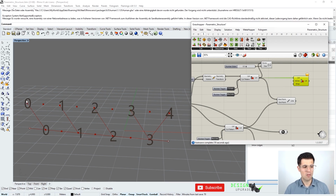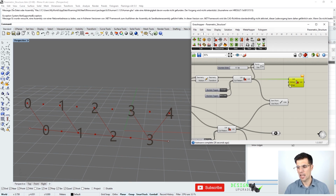The trick is that if we have this first index at 0 and we go backwards, we can get to the last item. So if I type -1 into quotation marks here, what we are going to do is define it inside of a panel, but it's the same for us. Now you can see how we are removing the last item, and this is happening because we have this graph parameter set as true. Otherwise, we couldn't get backwards to the last item as we have just done.